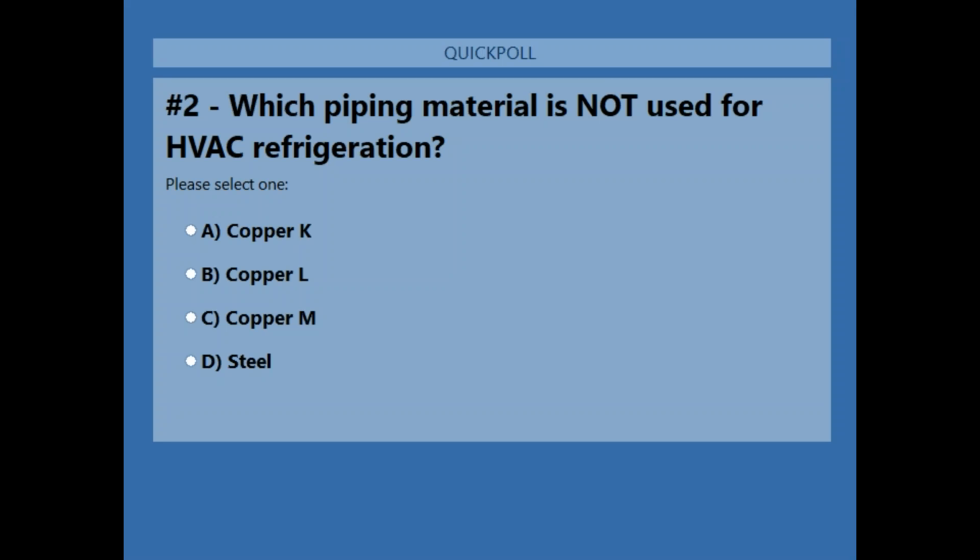Now, what I didn't mention is a lot of our coils come out intertwined. So with an intertwined coil, if you've got dual circuits, there is no first on, last off concern in a row split arrangement, because they're intertwined. It doesn't matter, but always make sure of what you've got. If it's intertwined, we can tell you that.